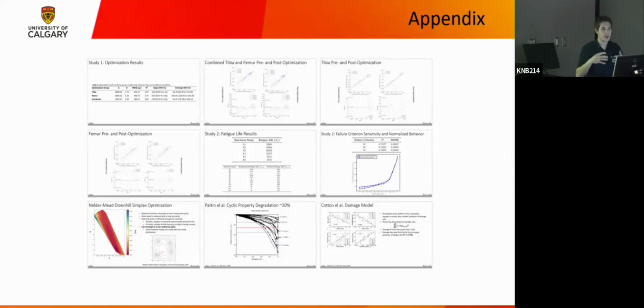So just reading it into memory, doing all of its data checks on that. If I could cut that time out, this would be twice or 3 times as efficient. Doing it on a supercomputer wouldn't affect that input file processing time. What it would affect is getting those finite element results quicker, and we could probably run the script a little bit quicker. But that script only takes about 10 seconds to run. It's that initial input file processing. It's super frustrating that it takes 5 to 7 minutes. There's nothing that I know of to bypass that other than doing a UMAT, developing our own FE method.